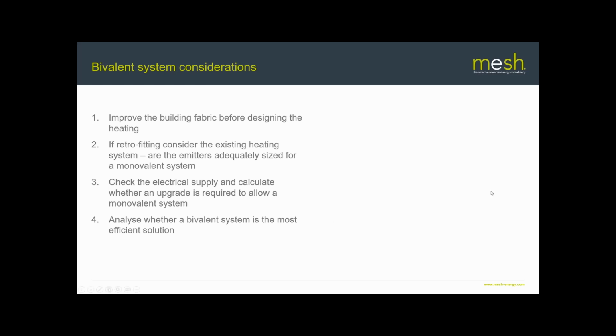But if you're talking about simple economics, it may be that in some cases a bivalent system can be more economically efficient to run than a monovalent system, especially in an existing retrofit type situation where you've got radiators that require quite high flow temperatures.